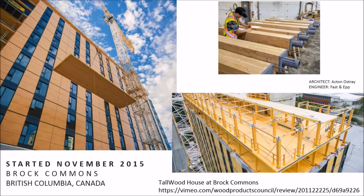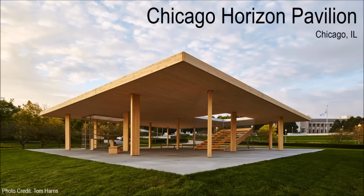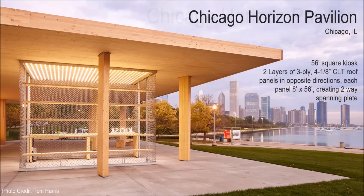But where we see this two-way spanning capability used the most to date in CLT systems is creating a beamless cantilever roof. This project in Chicago took that to an extreme, where it's a pavilion with a CLT roof supported on isolated columns with no other framing at all. But you can imagine this being at the corner of a building where you have a roof spanning off the corner in two directions with no supporting beams. Here's another picture of that really attractive pavilion project right on the lake in Chicago.